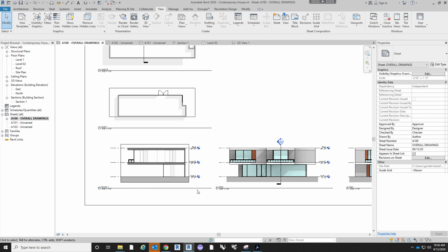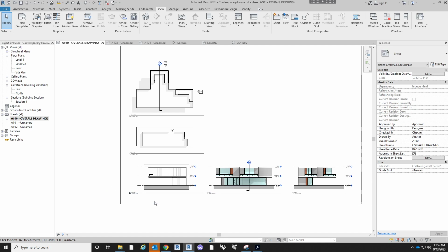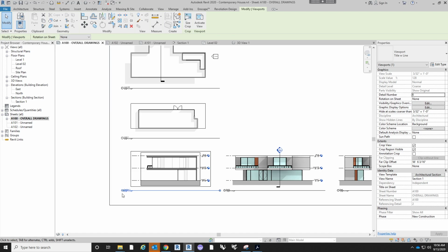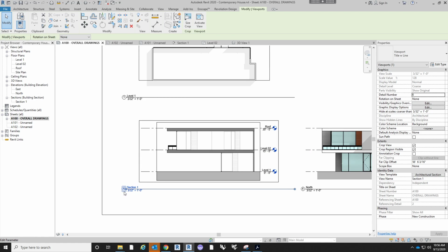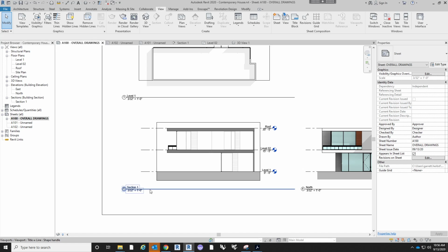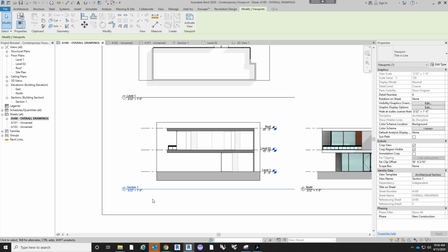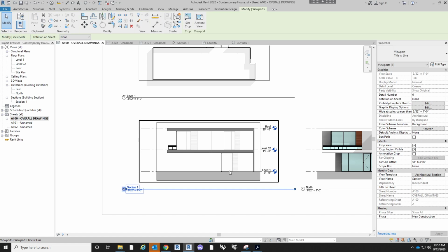And just real quick, since we have this somewhat organized, we can go in to change the name or change the number. What you got to do, instead of clicking on the actual name itself, the title name, you got to click on the drawing just once, and then it'll highlight the drawing name, and then you can click on that and change the name, and you can click on the number, change the number.